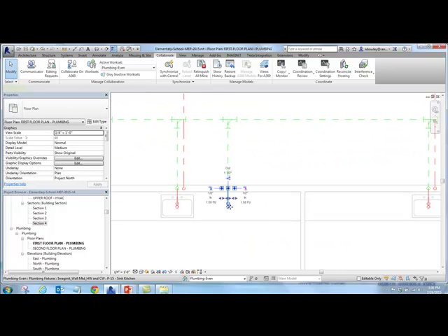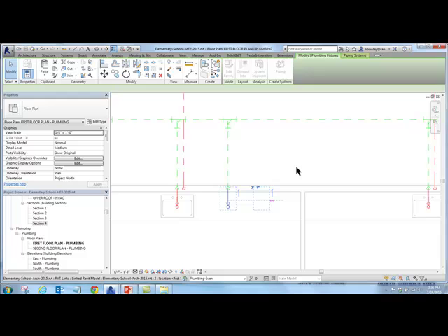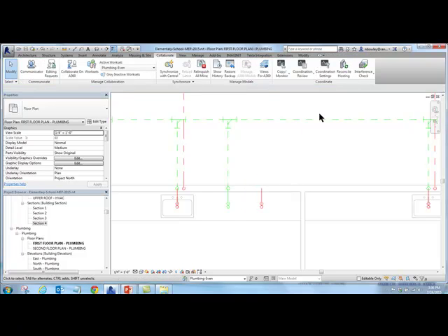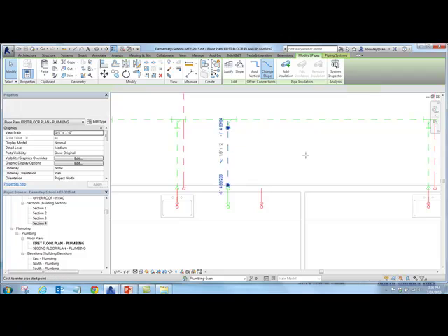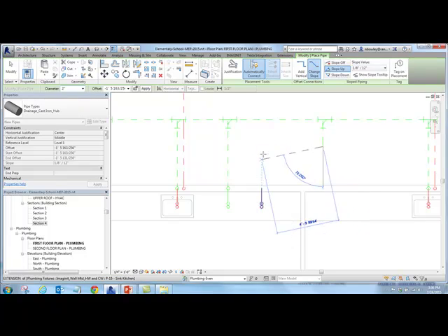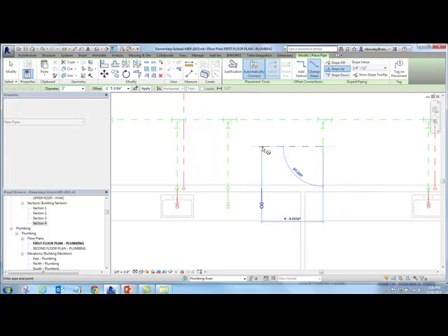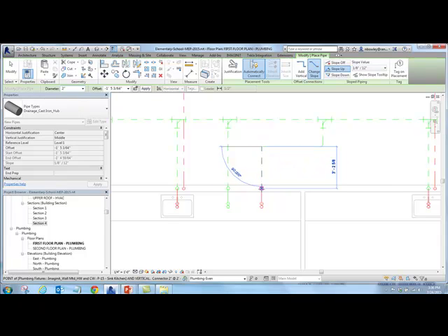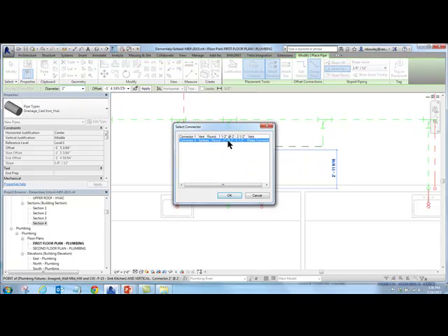Alternatively, if you're connecting your sinks, the old CAD way of doing it, at least for me, I would draw a main, and then I would go from my sink to the main. That doesn't really work as well with Revit with slope piping. So what you want to do is start at your main, use inherit elevation, slope up 1/8 inch to a foot, and that's going to come right off the side of the main, and then you can go toward your sink, and when you're going toward your sink, it snaps to your sink. In the CAD days, people didn't really use the snap extensions, so they would start at the sink just because they knew where they were coming from. But this works a lot better because it starts at the right elevation to connect to your main at the side.